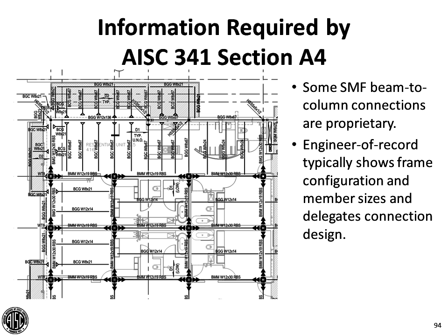Now, there are some special moment frame beam to column connections that are proprietary. And when I use the word proprietary, what I mean is that there is a patent on the connection itself, and the owner of that patent will license others to be able to either use or fabricate that particular connection. And there are several that are proprietary that are listed in AISC 358. So what I want to do is just briefly show how many engineers deal with this particular issue.